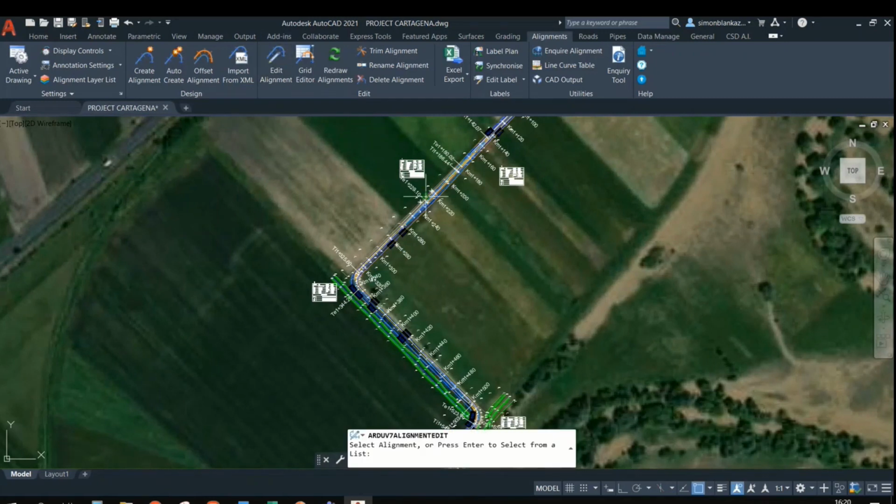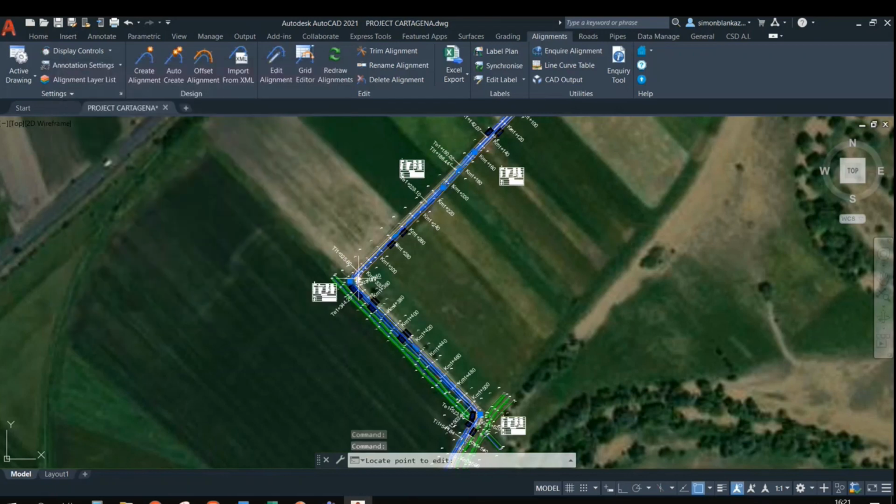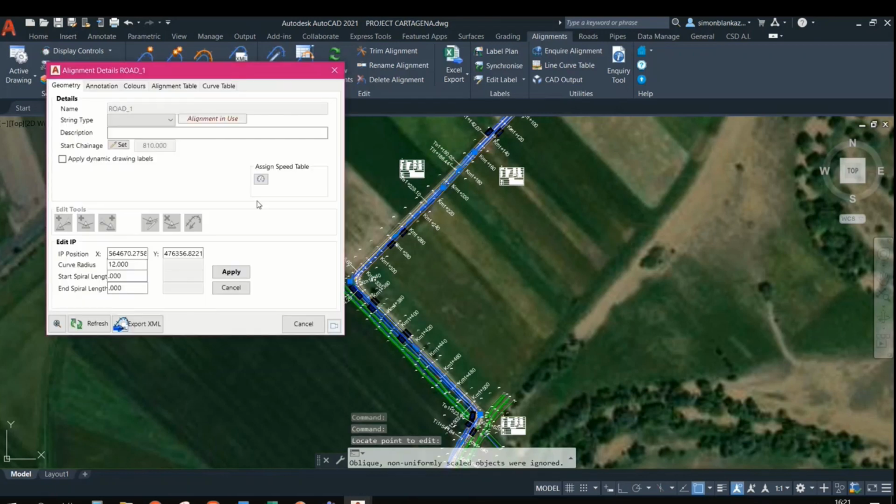So I go with the Edit Alignment tool. Here you can add IPs at the end or at the beginning or in the middle. You can move IPs, delete them, or reverse the chainage. And to add the radius of the curves, you go with this button and select any of the IPs. You can introduce the curve, the spiral length, the end, and the...